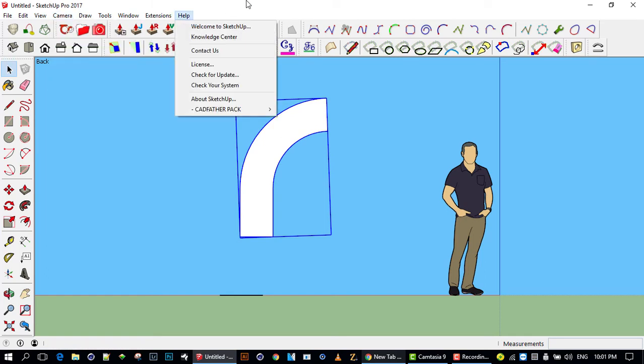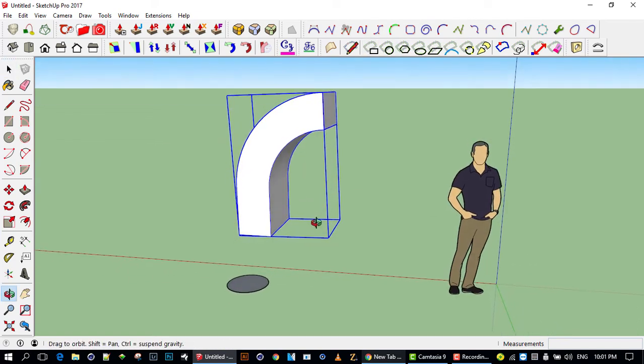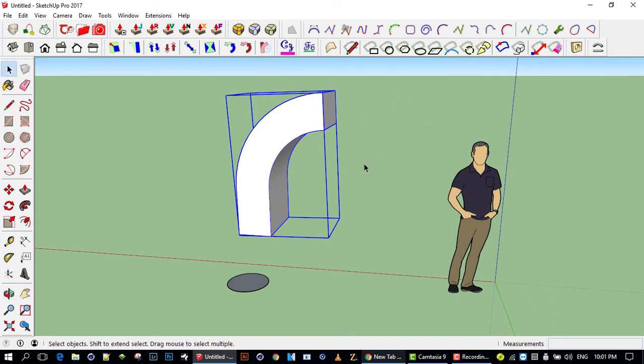In this way, I can draw using Beziers and keep it in one plane. Because if I draw with Bezier curves or any other kind of curves while I'm in the perspective view, I could be drawing and it could be going back and forward, and I wouldn't know that. So this is quite essential.